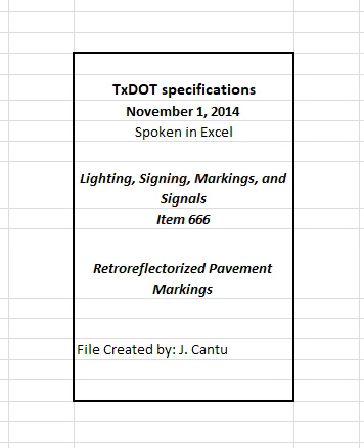Follow the manufacturer's directions for application of acrylic or epoxy sealers. Clean sealer that becomes dirty after placement by washing or in accordance with section 666.4.2.1, Cleaning for new asphalt surfaces and retracing of all surfaces, as directed. Place the sealer in the same configuration and color, unless clear, as the Type 1 markings unless otherwise shown on the plans. 4.3 Application. Apply markings during good weather unless otherwise directed.